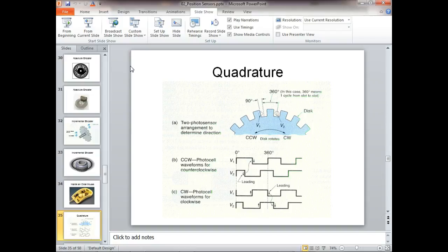I don't know if you've ever been in a plant before. There's a lot of vibration going on. And the motor's sitting there vibrating, right? You understand? And it could cause that thing to be going back and forth. And every time it did that, it would do what? Count. So a lot of times they'll use a quadrature encoder, and they'll reference it to one of these, like